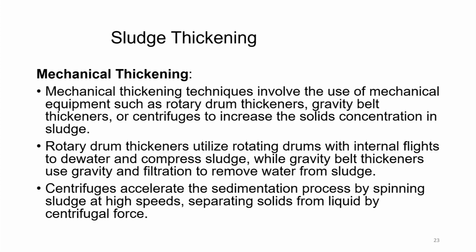Mechanical thickening. Mechanical thickening techniques involve the use of mechanical equipment such as rotary drum thickeners, gravity belt thickeners or centrifuge to increase the solid concentration in sludge.